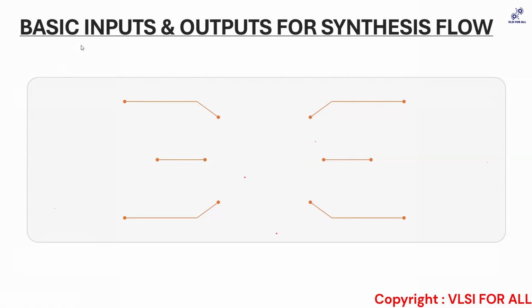These inputs are RTL, dot SDC, and timing as well as physical libraries. And outputs are gate level netlist, log file, as well as the reports for various things like timing, power, area.